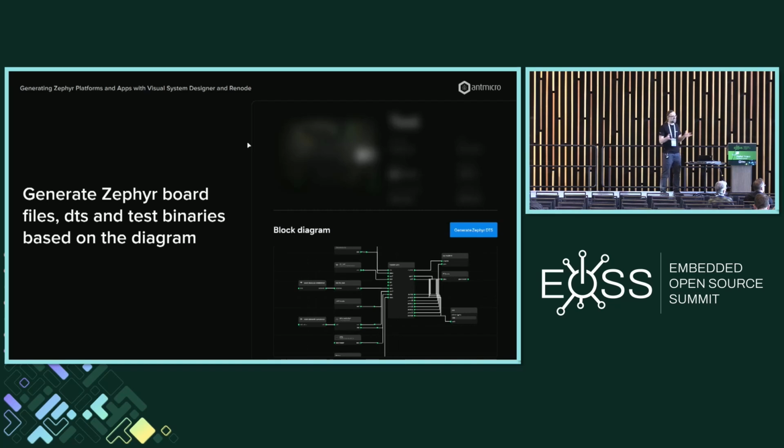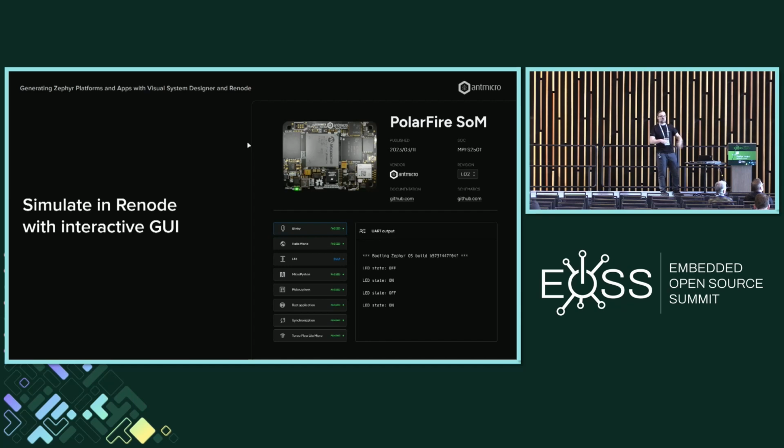So with some clever heuristics, you can get very good coverage of different kinds of systems. And we can generate binaries for quite a lot of different SoCs connected to different sensors, and it just works. And when I say it just works, it's because you can then take those binaries and actually run them in simulation. Because as you remember, if we have the device tree, we can also generate a simulation file. So you put those two together, you get a full feedback loop.